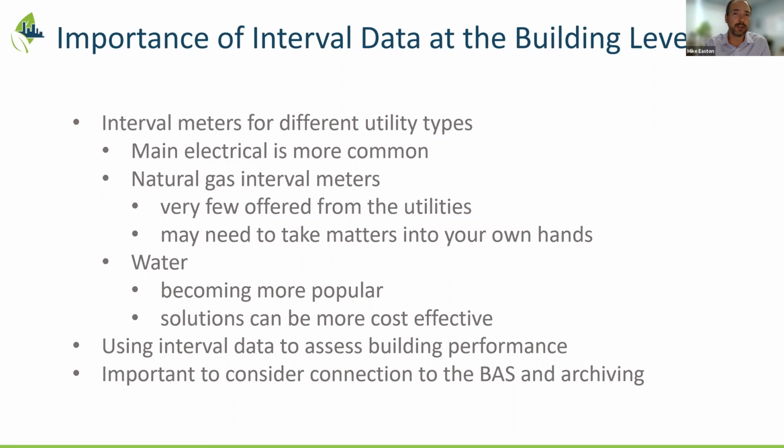We find this upgrade usually ends up being somewhere between $3,000 and $5,000, because you need the modules and some labor to get that work done. If you're in a jurisdiction where the utility does not allow their natural gas meter to be upgraded, you typically would go with a redundant meter, probably an insertion meter on a larger load. These are fairly accurate and fairly easy to install. They're not a revenue grade installation, but nonetheless, they're a good balance between cost and accuracy. We've been doing a lot of our redundant building level gas meters as insertion meters lately.